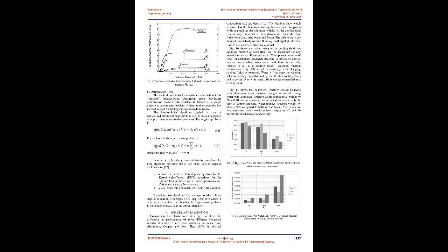B. Cell topology. There are three basic distinctive features that differ between periodic corrugated sandwich structures. The first and most visual feature is cell type. Corrugated structures could be hexagonal, square, triangular cells. The second feature is stacking order. For example, structures with triangular or square cells, Fig 7, are different in performance due to different connectivity points.